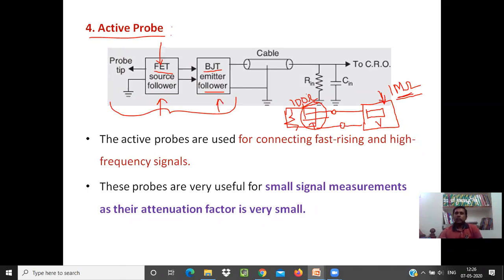So that's why, whenever you use an additional measuring instrument to measure the output voltage or amplitude of a circuit, it should have a very high input impedance. That's why we commonly say that in electronic circuits the measuring instrument should have a high input impedance and a low output impedance, right?